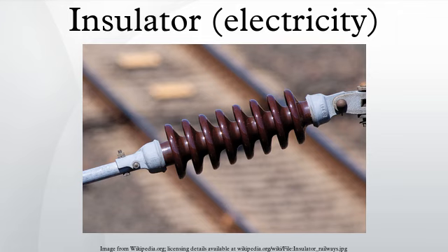Design. The electrical breakdown of an insulator due to excessive voltage can occur in one of two ways. A puncture arc is a breakdown in conduction of the material of the insulator, causing an electric arc through the interior of the insulator. The heat resulting from the arc usually damages the insulator irreparably. Puncture voltage is the voltage across the insulator that causes a puncture arc. A flashover arc is a breakdown in conduction of the air around or along the surface of the insulator, causing an arc along the outside of the insulator. They are usually designed to withstand this without damage. Flashover voltage is the voltage that causes a flashover arc.